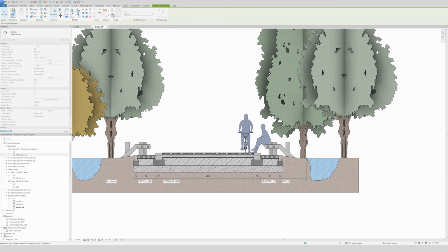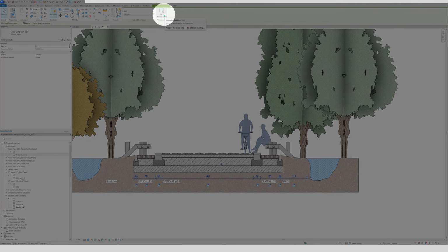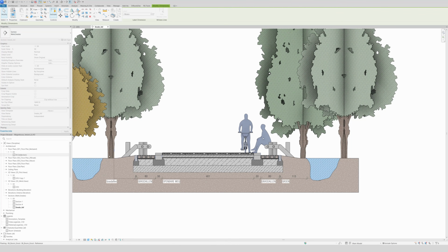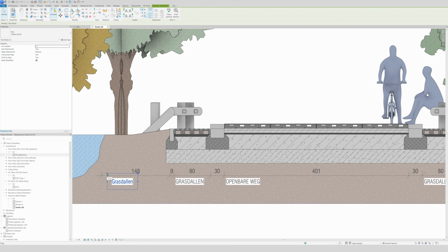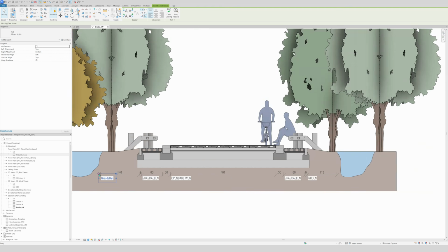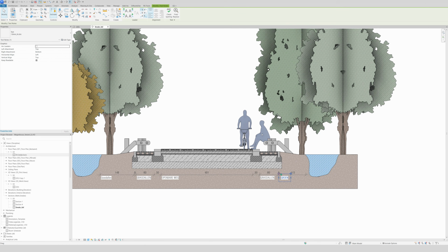I will use the tab key to get there, and then just click in the white space right here, and the dimension will be added. We're gonna do the same again to the other side. So right here we go to witness lines again, and then gonna click the dot. Now again to the white space, and voila, you added some dimensions to the dimension line itself. And I'm gonna place it right here, and I'm gonna place it right here. Gonna change the name in a second.